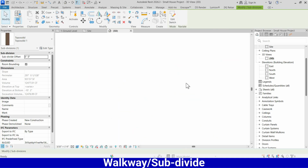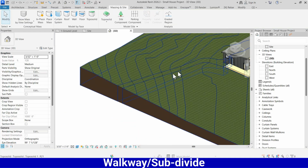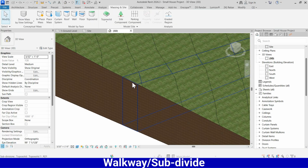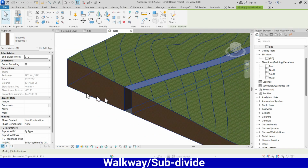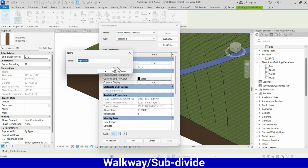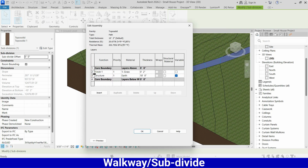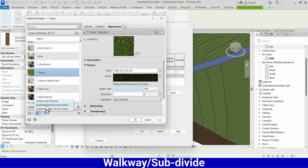And then make it checked. If you see in the 3D, it's the same grass. We have to change the material. What we'll do is click it and go to the edit type, then duplicate and name it path or walkway, and then structure edit and delete this one. We don't need this. We have to change the grass. We need some path here.